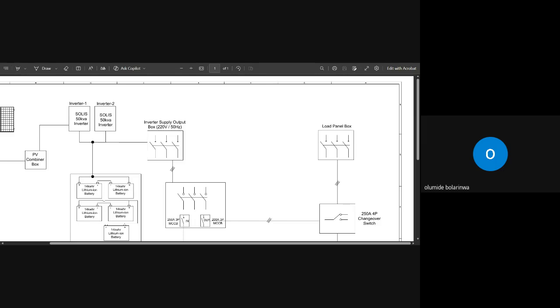There must be a connector that will connect your red cable together and your neutral cable together. You know how they usually do it: you just take 2 cables, lump them together, and wrap insulation tape around them. It's not done. There must be a connector between them.